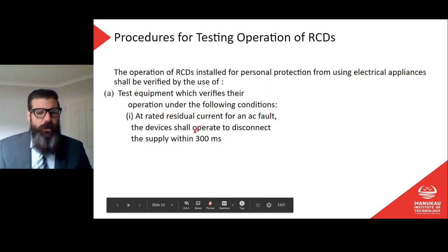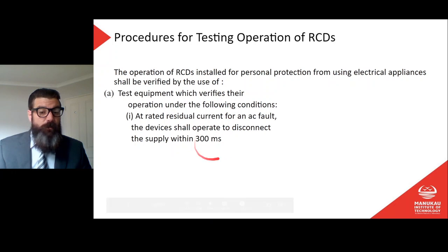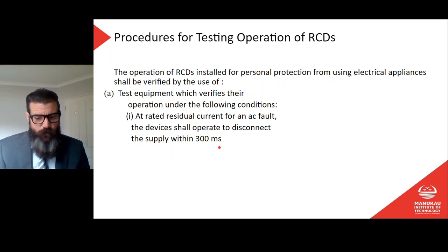Okay, 300 milliseconds at rated current, which is 30 milliamps. Remember, this is slightly different for those other ones, the 10 milliamp ones for schools and medical facilities. So remember to check the correct ones.